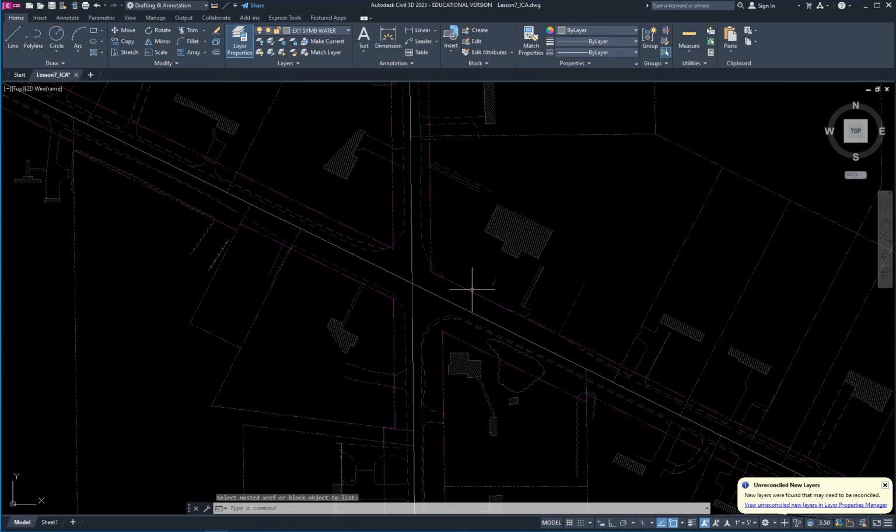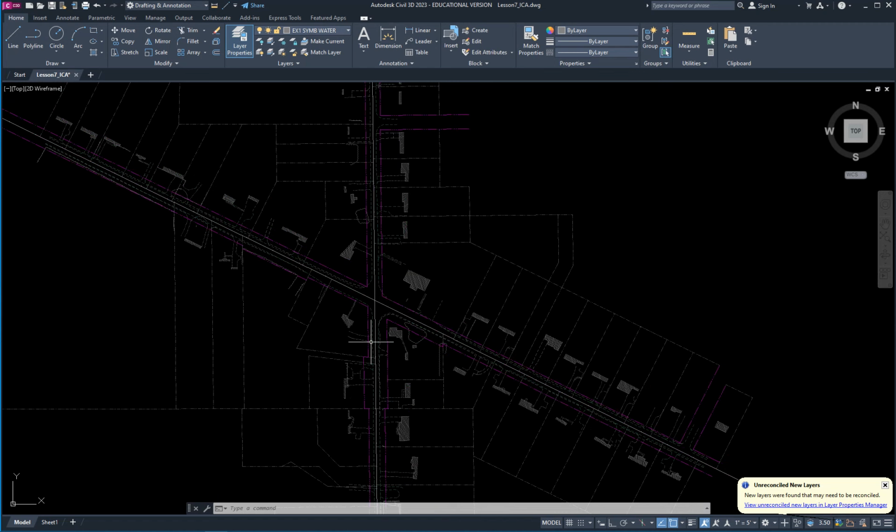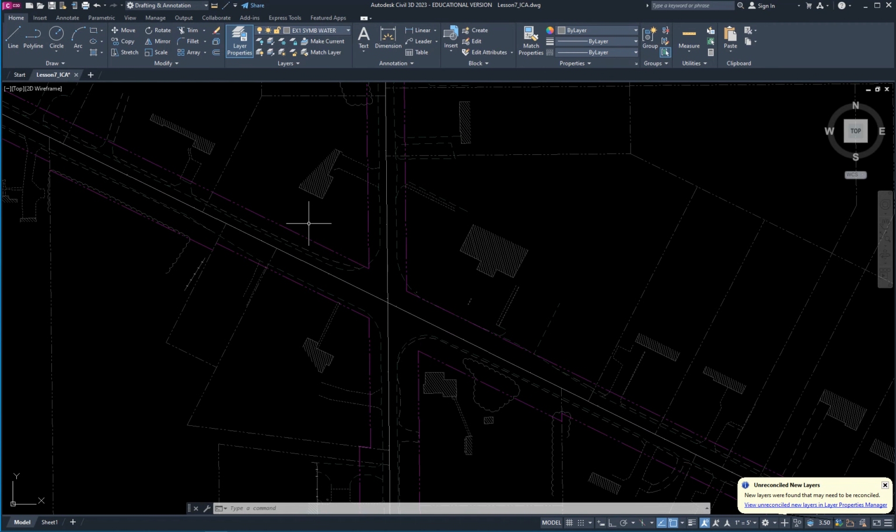If you have multiple Xrefs, it's nice to see that front part, because it tells you exactly which file this line work that you're seeing is coming out of. If you want to go in and fix something or look at it offline, I guess, it can tell you how to find that. So that's pretty nice. I use that quite often.